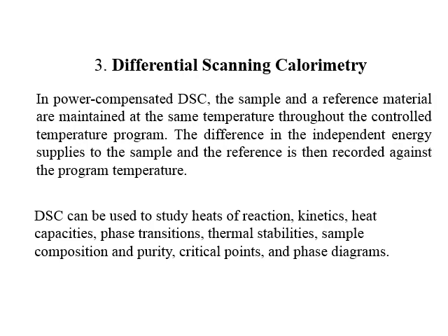You have to think about that a little bit. It's not necessarily straightforward, but depending on the material in the sample, it will require more or less energy to maintain that temperature than our reference material. And by measuring that difference, we can identify what's going on inside of it, whether a melting event or a crystallization event is occurring, depending on whether heat is flowing into it or out of it. DSC has a broad application. It can be used in the study of heats of reaction, kinetics, and heat capacities. It can be used to develop phase diagrams, determine thermal stability, sample composition, and so forth.